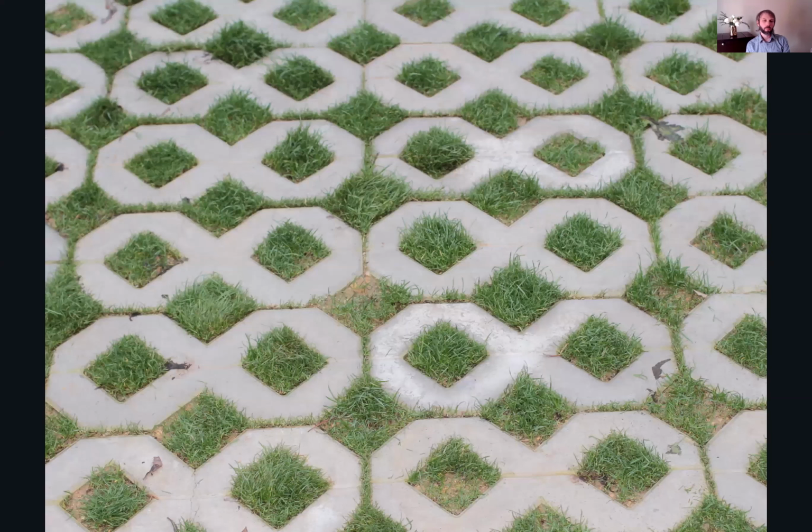And then back to the stormwater piece, we're talking about permeable pavers. So we can convert all of our concrete over to permeable pavers and have water infiltrate the ground. We've seen this go into rainwater catchment features or rain gardens, but make sure again that it's not getting into the stormwater and it's getting into the ground and it's not causing flooding through certain types of permeable pavers.